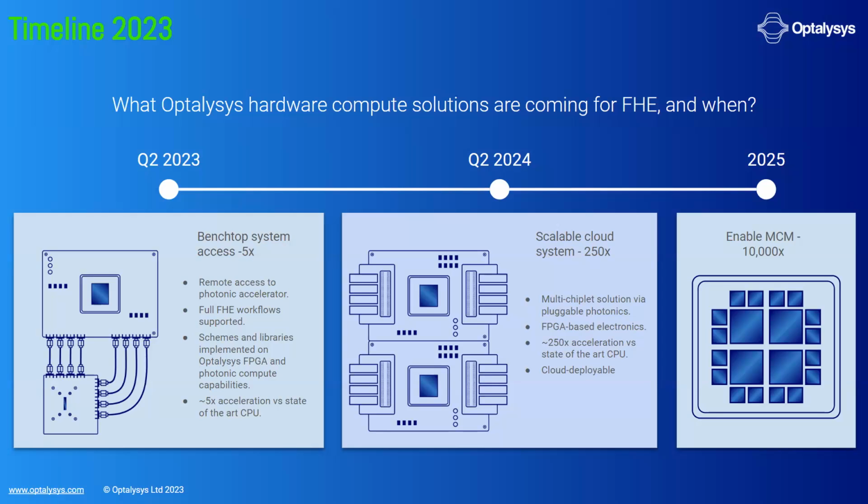If you think about pluggable transceivers in the context of data center data transport, those systems already have a lot of the supporting infrastructure that is needed to transfer data to and from a photonic component at very high speed. So the next step is to create transceiver type pluggable photonic compute units that can interface with an FPGA over pluggable mezzanine cards.